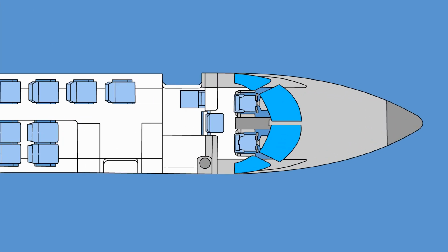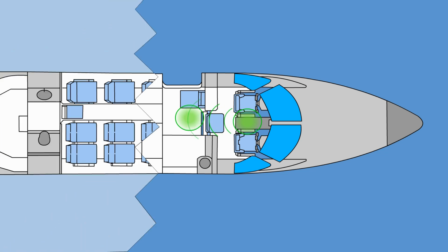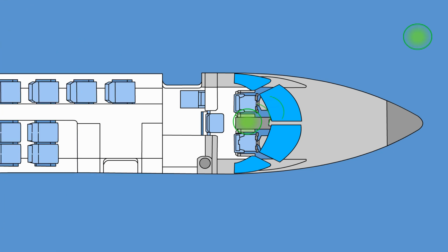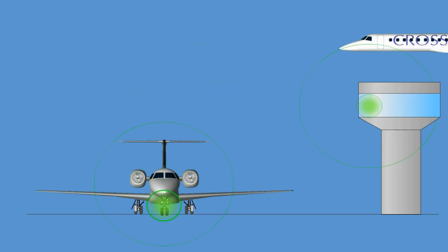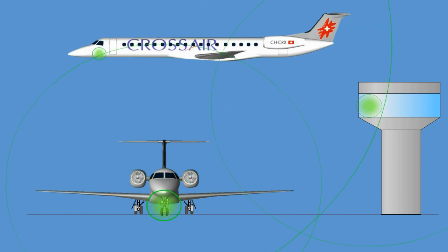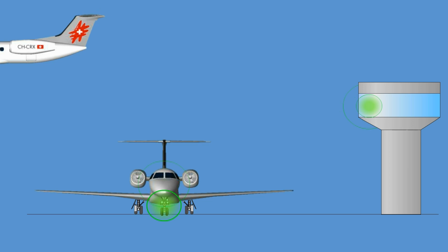The Embraer 145 is equipped with an audio integrating system, which allows two-way interphone communication between the cockpit crew members, the cockpit crew and the forward flight attendant or rear flight attendant, between the cockpit crew and the front ground crew station, and or the rear ground crew station.